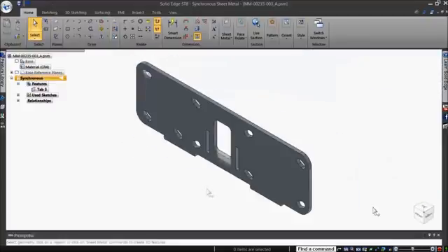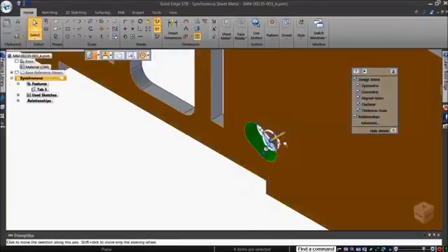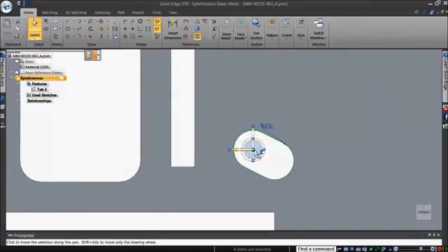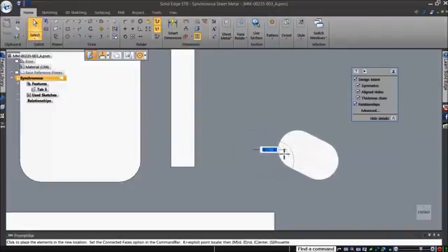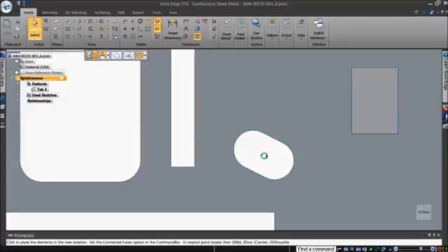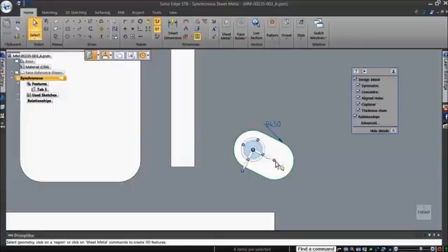But there's more. By default, the steering wheel aligns with the selected geometry, and this may not always be desirable. To accurately rotate the steering wheel into the desired position, shift-click on the end knob to allow it to rotate in the tool plane. Mouse position can also be used to input the inferred angle if you want. Rotate the steering wheel to the required angle and use it to make your intended modifications.